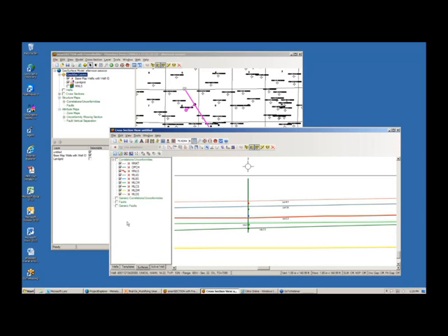The Surfaces tab is where we actually see which surfaces we're working with. You can highlight a surface and you'll see these little squares appear here that will highlight that surface in the cross-section. You can actually click on a surface, do a right mouse button, go into Display Properties and change the color, weight, and style of that surface. You can also turn a surface off if you don't want to see it. So basically it's kind of surface management, if you will.